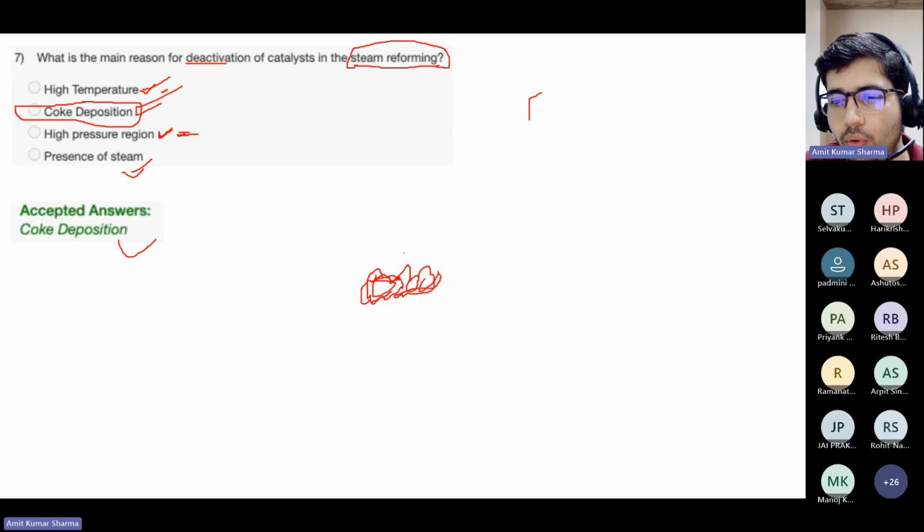Whenever you want to have a steam reforming reactor, you need to know the catalyst, the required feed velocity, feedstock availability. These things are very important. The temperature and the pressure will affect the reaction kinetics. For each different type of catalyst, it can be different. So the best thing is to model the reactor.